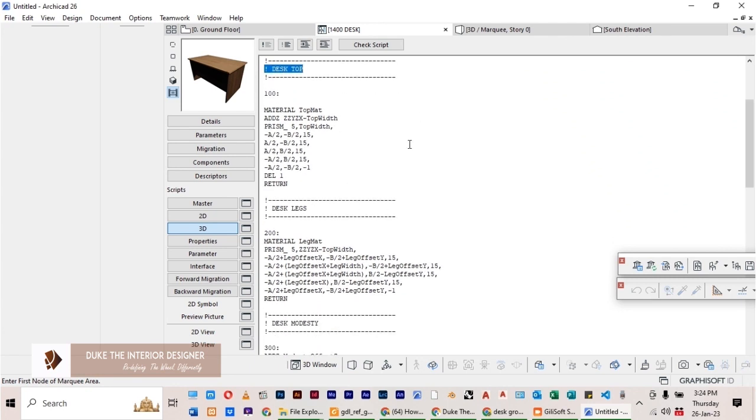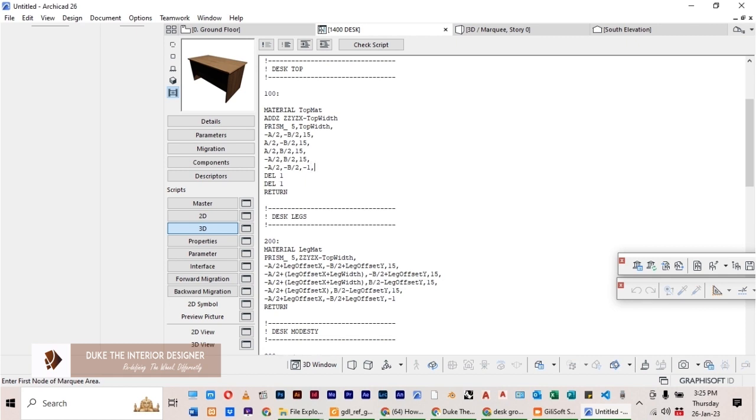So normally what we need to do is to add two codes when you're using the prism method. The first point will be defining our center point for the circle. And the center point of a circle, instead of finishing with a status value of 15, we do a value of 900 plus 15. The 900 is the one that does make the center.